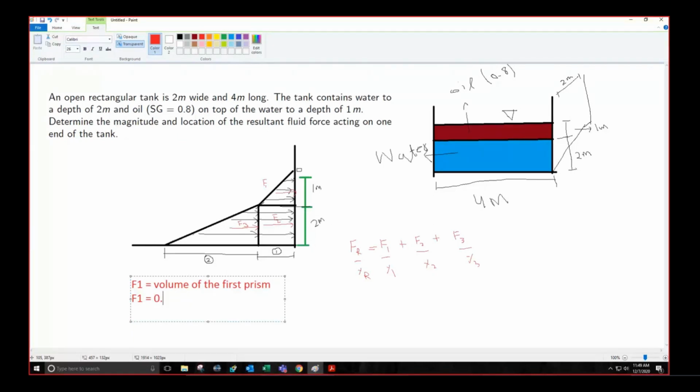The base of the triangle, which is 0.5, multiplied by the specific weight of oil. Let's write it as gamma oil. So multiplied by height square, which is 1 square, which is H1 multiply. This is the half base into height, again H1, right? Yes sir. Into the depth, that is the width of this tank, which is 2 meters. ठीक है? समझ आ गई बात?